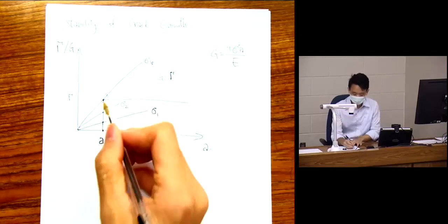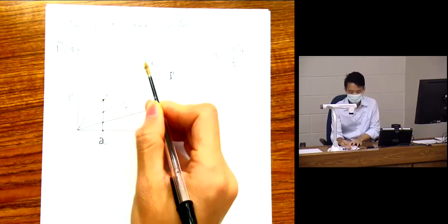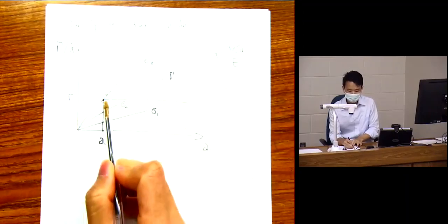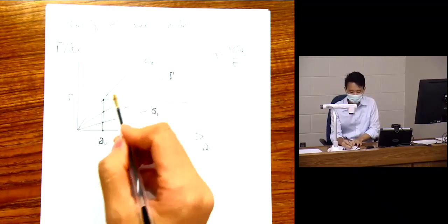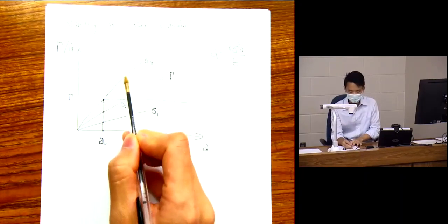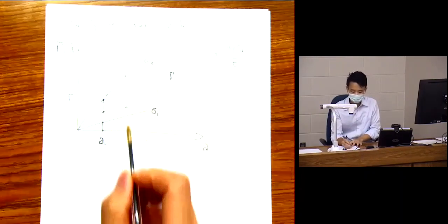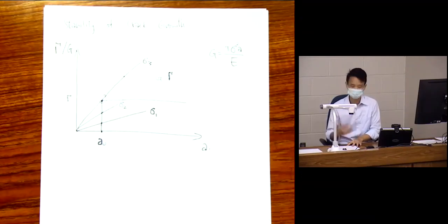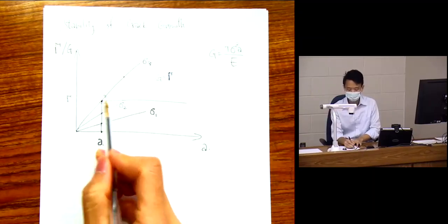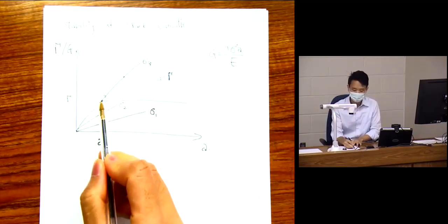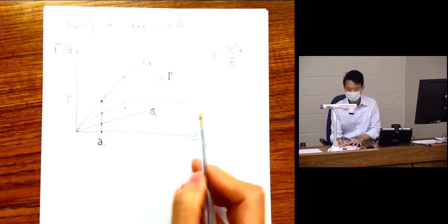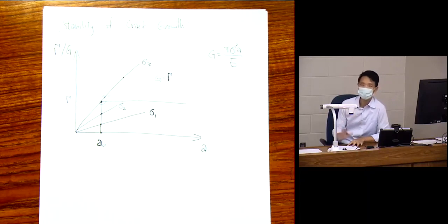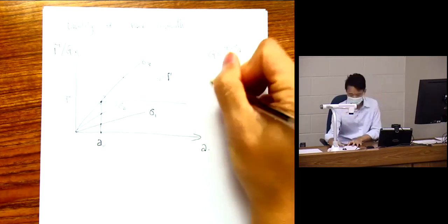Now what we need to look at is the same curve, because I'm applying sigma 3, and my gamma does not change. So what I have to look at is what happens afterwards. My G is going to keep increasing, my gamma stays the same. So that condition is being satisfied all the way. Once it's satisfied initially, it's satisfied all along afterwards. That means the crack is going to keep growing. This is unstable crack growth.